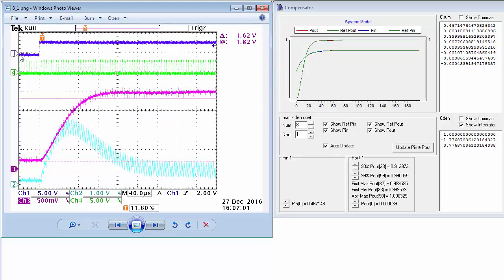The top trace is the scope trigger. The next trace is the PWM timer pulses, basically the plant input. The next trace is the buck converter output voltage. And the bottom trace is a current probe point in the evaluation kit. Each pulse represents one 5 microsecond cycle.